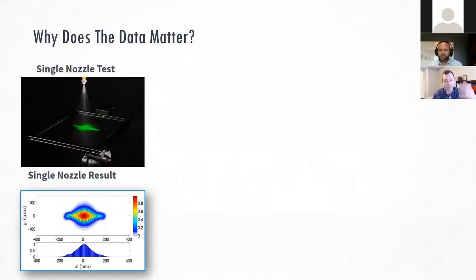Yeah, you can imagine whether it's a hydraulic spray or more importantly, like with an air atomized spray, we have this air moving along with the liquid. You can't necessarily collect this type of a spray pattern in a trough or in a collection tube because the air is going to move those droplets around. And so laser sheet imaging, like you see here, is something we use to assess the 2D spray pattern as well as create a 1D spray pattern as well.